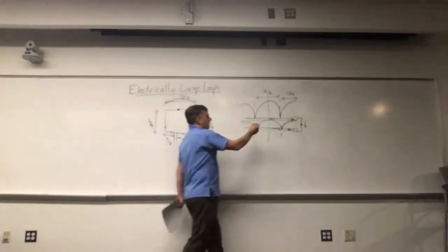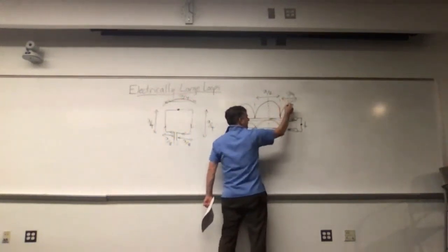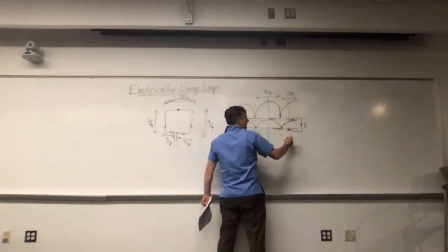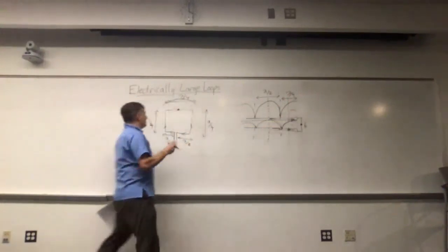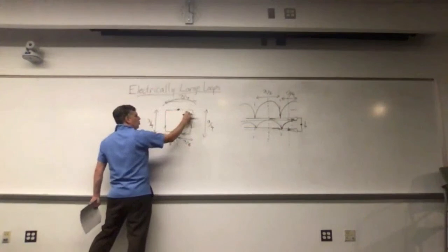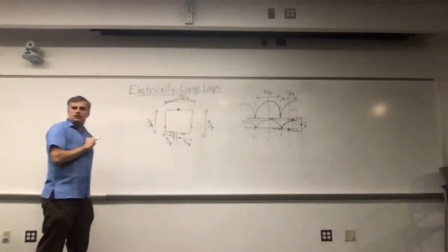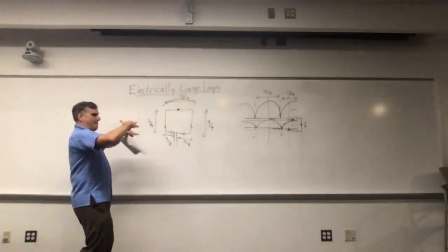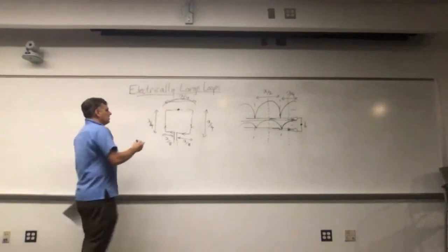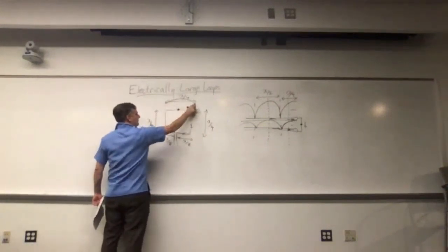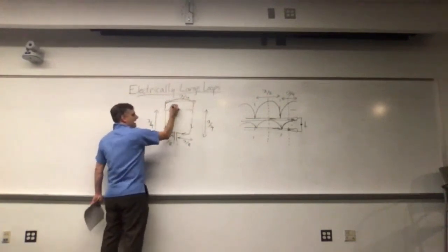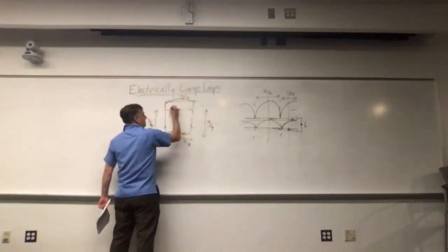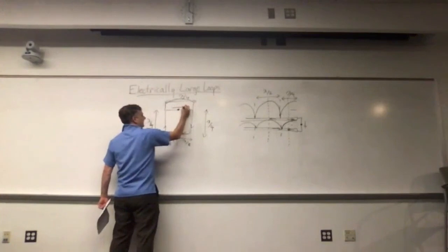I've got 1/8 of a wavelength on either side that constitute this quarter wavelength section of wire that I bend out. So it's not a full hump of sinusoidal current, but it's the biggest central part of the current. And according to this diagram, it's going to be going this way.